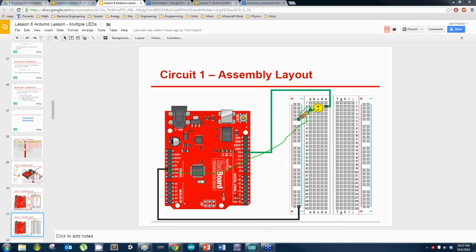What you can do is this is the green wire from this ground. I'm just jumping it over to here, to the bottom part here, and then you can just take the resistor where you had it plugged into the green wire and then jump it over to here. Does that make sense?